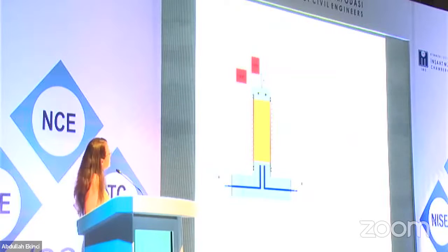At the initial state, a highly saturated sand sample is installed by pouring a sand-water mixture using a funnel into a supported rubber membrane. At this step, at the initial state, the pore water pressure is equal to 0. The effective stresses are equal to 0 if we neglect the self-weight of the soil. And the only pressure that is acting on the specimen is the relative air pressure in the testing facility, and this is also equal to 0. The relative air pressure remains constant and unchanged during the test and represents the total stress during the test.